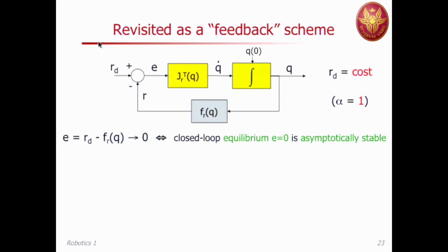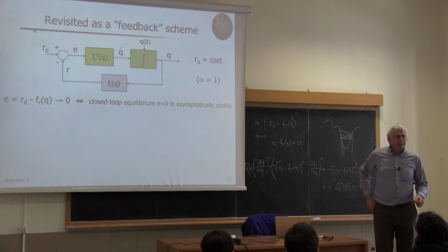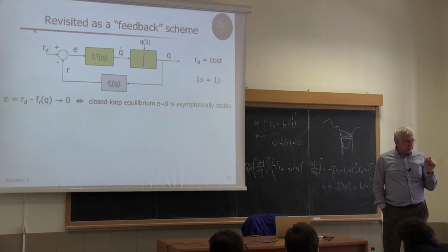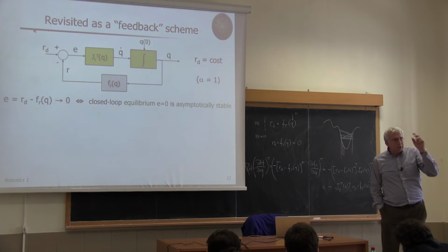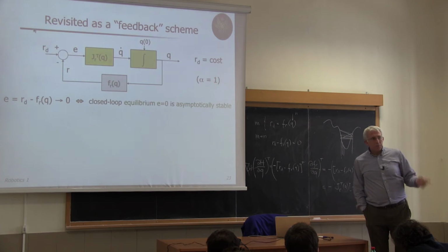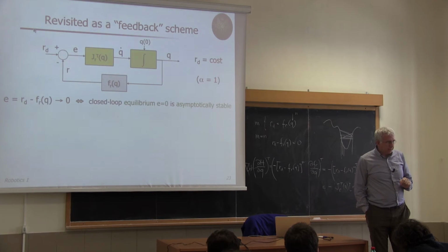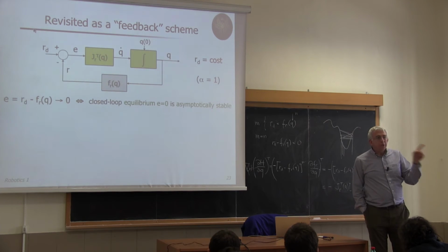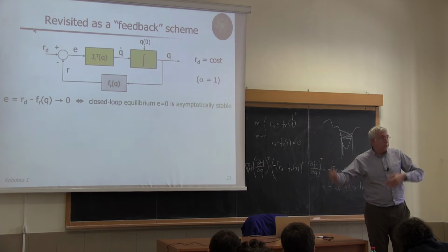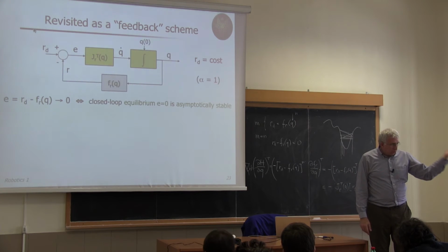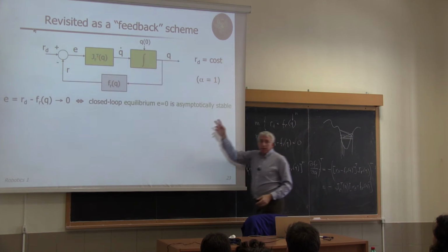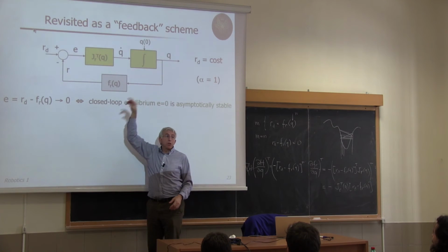Now, probably you don't realize this, or nobody explained it in this way, but you should think that if you have a feedback system which is asymptotically stable, so it converges to something, it will automatically invert from the input-output point of view what is in the feedback path. This is why we refer to unitary feedback, because if the feedback is unitary and we are inverting this, then the output will be equal to the desired value, which is put in input to our controller.